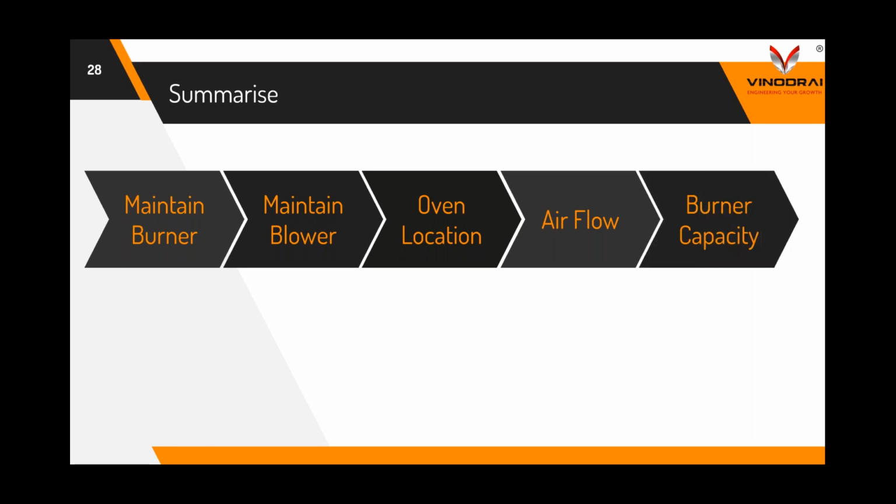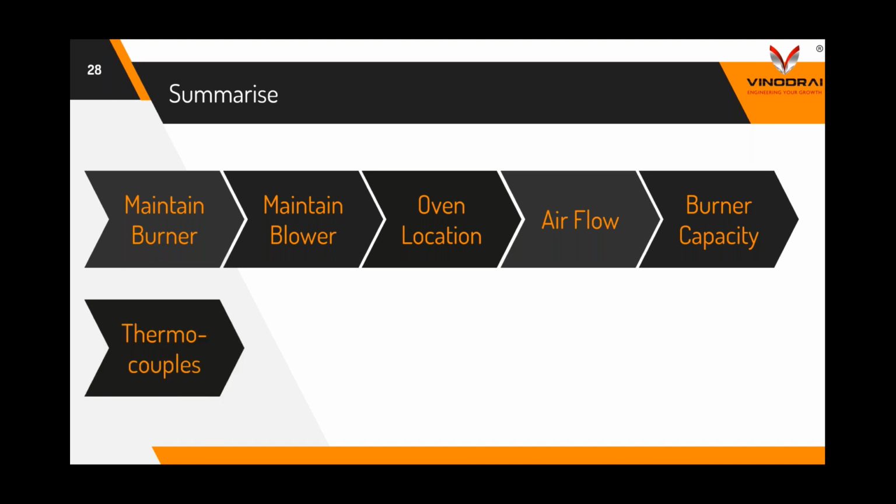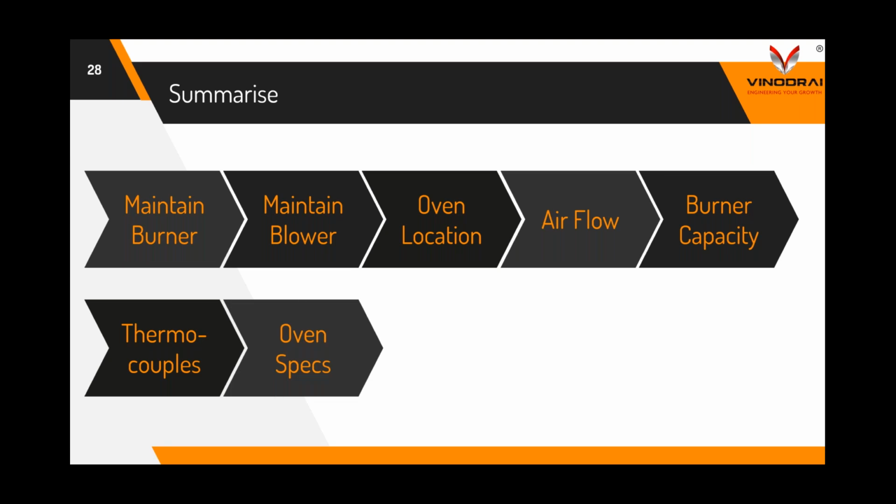The burner capacity needs to be correct. You need to consult your manufacturer to know the right burner capacity for your oven. I think thermocouples play a very important role, and cleaning them regularly and maintaining them regularly is very important.